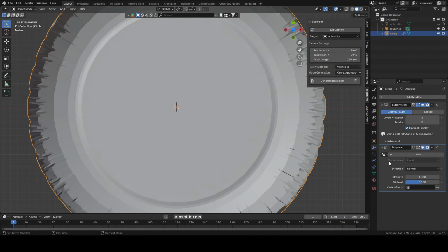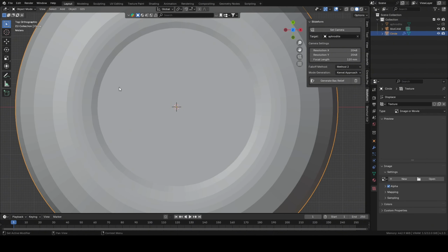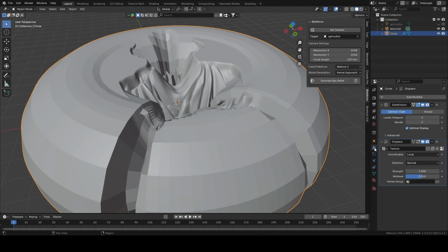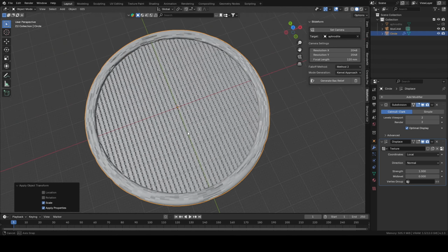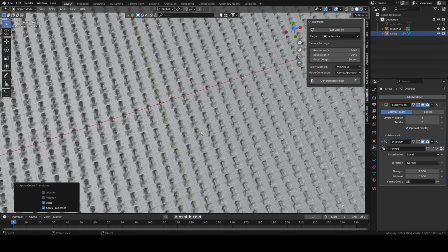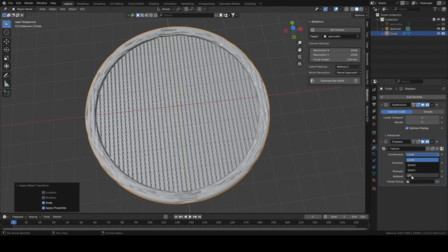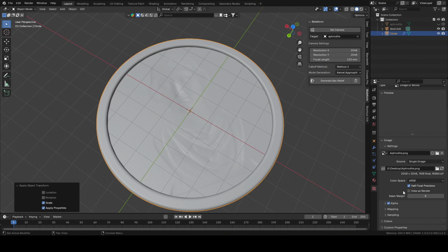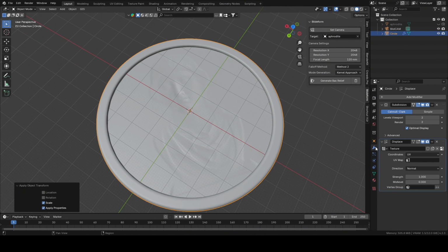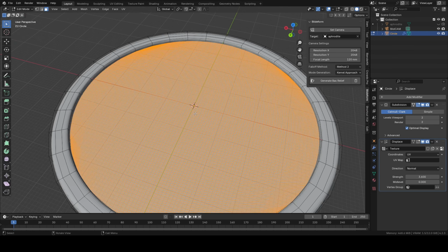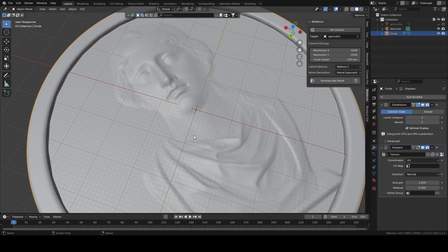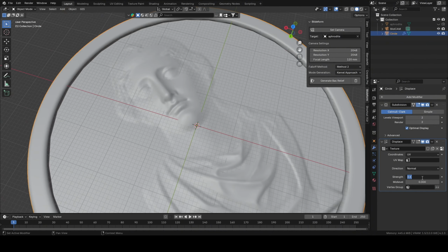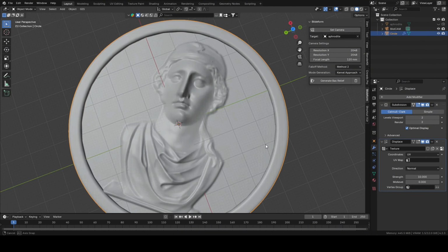Now, with the example coin created, first, we go to New and open our image. Here, we modify certain parameters, like displacement, and adjust the scale as needed. We also switch to UV mapping to avoid any issues with the geometry, and set the mapping mode to clip for a more precise outcome. Once these settings are in place, we increase the effect strength and recalculate the normals to ensure everything is aligned correctly. At this point, we can start experimenting with the adjustments to suit our preferences.